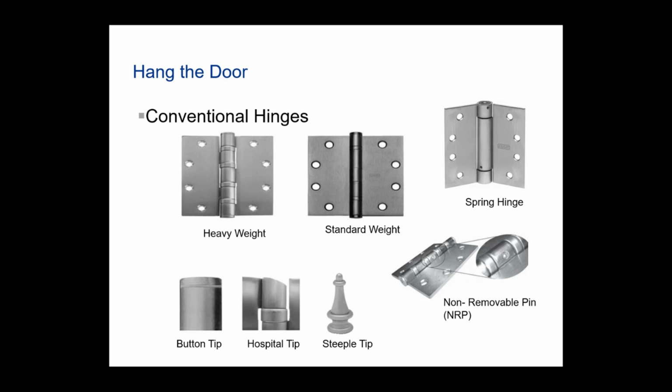Spring hinges are ideal for apartments where they have to be 20-minute rated, and that the front door of that opening has to always close. We'll get into fire rated openings a little bit later. But they can also be used at exterior uses, such as gates or doors at exterior uses, especially not highly rated, or doors that don't need to meet ADA, places like that. Spring hinges are a very good application and a very economical application.